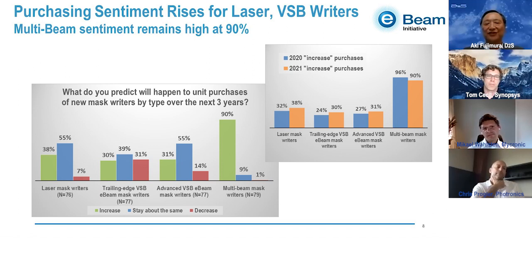Yeah. Right, for the mask writers, yeah. What do you think about EUV masks going curvilinear? You said earlier that some kind of a hybrid approach, curvilinear for hotspots. What's the reason to not use curvilinear everywhere if it makes no difference because you're using a multi-beam writer? Ultimately, I think the fabs would like to use curvilinear everywhere if they have a multi-beam writer and it can handle it.